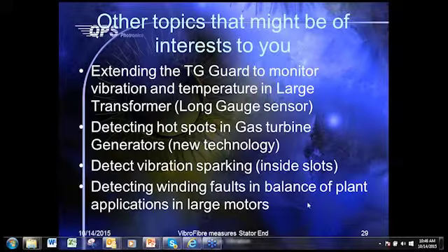In our conversation with some customers, who are very conservative in the design, they would, for example, keep 3 large motors, with 2 running at half load and leaving the third one as a spare. That did not help them in having failure. In fact, the condition monitoring solution that they have never showed them the winding problem. And whenever the motor failed, upon failure analysis, it was always the winding that was causing the problem.